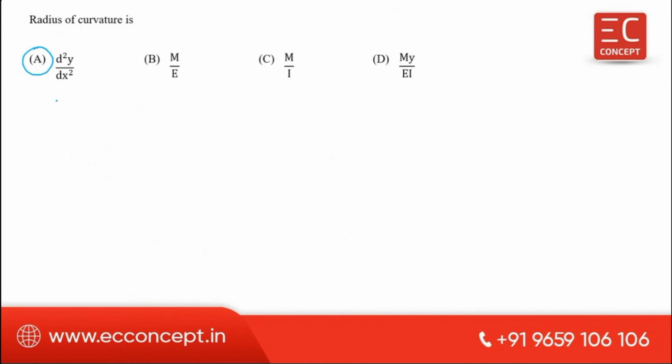We know that the formula M by I is equal to f by y is equal to E by R. In that you have to take these two, so that M by EI is equal to 1 by R. Now this 1 by R is called curvature. This whole term is called curvature.